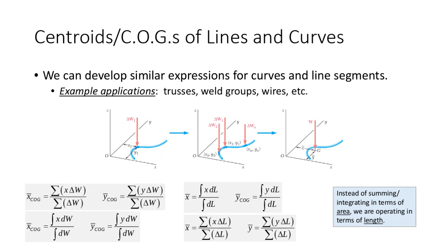The roof trusses had a very weird geometry, and when the crane was picking them up and trying to set them on the roof, because the trusses were of this very irregular geometry, they were kind of wobbly, and they were hard to manage and hard to lift. And I saw that, and I went, oh, they need to know where the centroid of that truss is so that when they pick it up, it stays stable. And I thought, man, that's a perfect example to mention in statics.